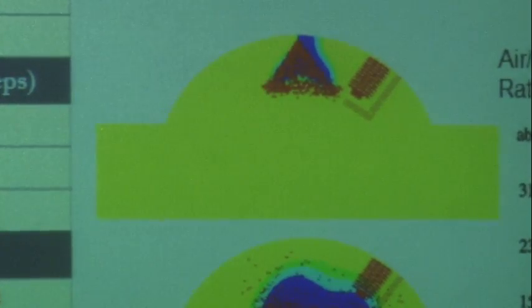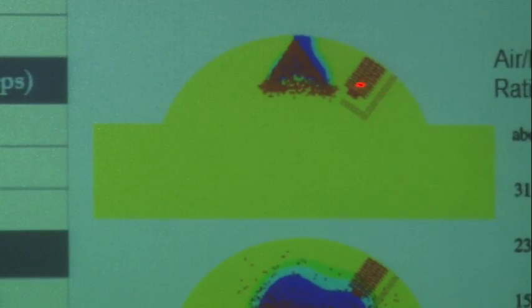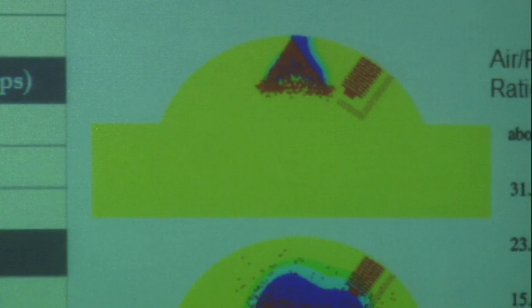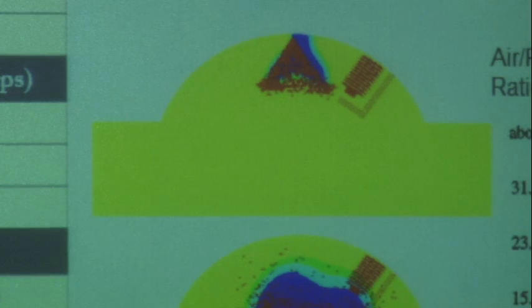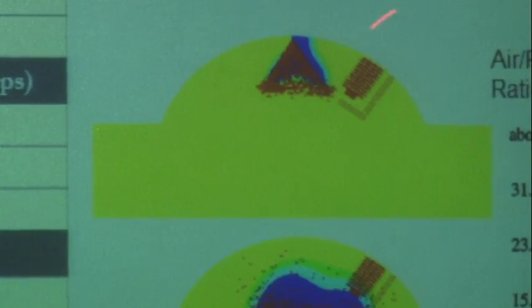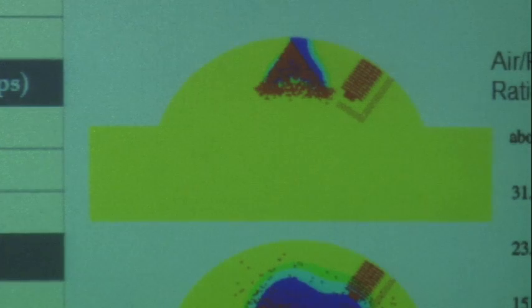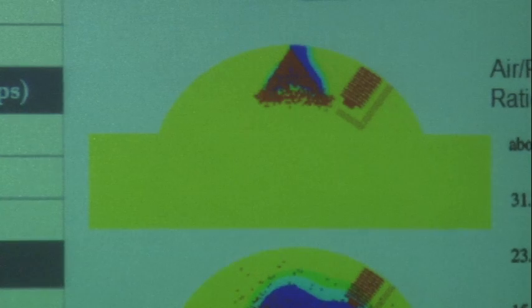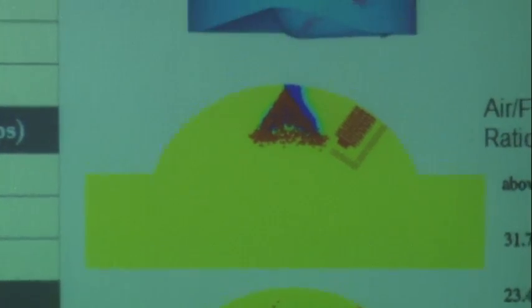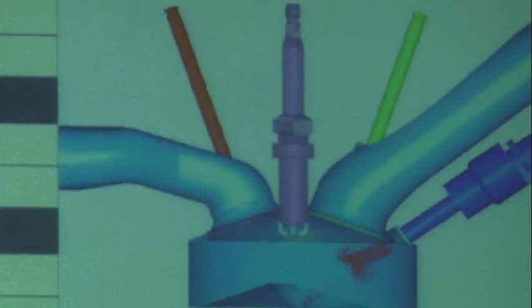We use the same spray model particles, except these ones are stationary, and we insert them in the domain in such a way that the boundary condition is enforced that the flow should have zero velocity in the vicinity of the spark plug. We do that by giving those particles a huge drag coefficient. So it's just a trick. You can represent a spark plug that way. Other people have even represented valves using particles in simulation. So it's just an interesting idea.